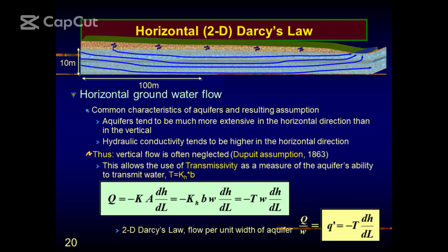If you remember, I clearly mentioned that confined aquifers are under pressure, isn't it? And that's why they have a piezometric surface. They are under pressure. But every confined aquifer has a source, an outcrop, where it receives recharge. Unless we are talking about fossil water, which I made mention of. Remember?